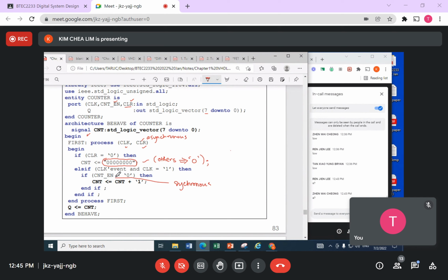Clock first, then only this one. So this is synchronous. I check my clock count enable here. If it's 0, active low, then I increment. Add 1 to it. And this one here is unsigned. This 8 bit here is also unsigned. The MSB represents a number instead of a sign bit.